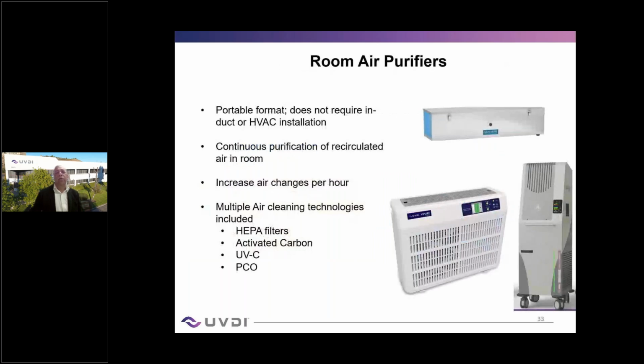And let's talk about room air purifiers. During COVID, there was a big focus on what can we do? What about schools and all? They were all grappling with what is an easy, ready solution to inactivate. And they were focusing more on bioaerosols and COVID. But room air purifiers, if they are designed correctly, can add multiple technologies. You can have a pre-filter followed by a HEPA filter. You could have activated carbon in there, UVC for air disinfection, and of course, photocatalytic oxidation.